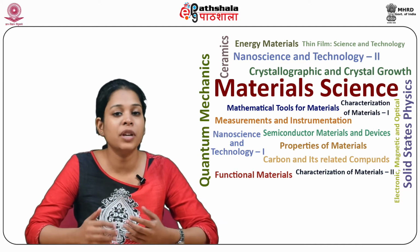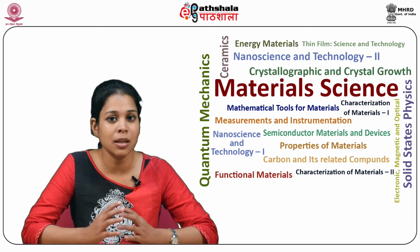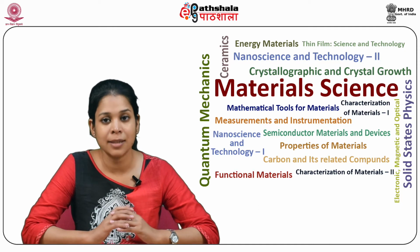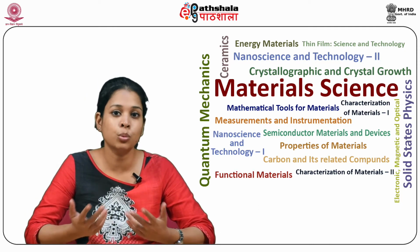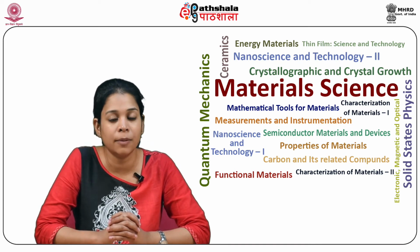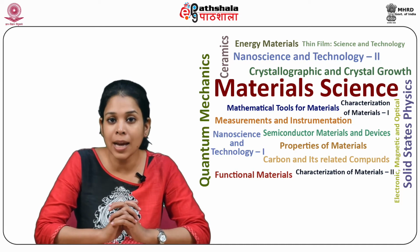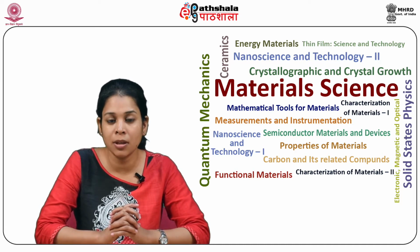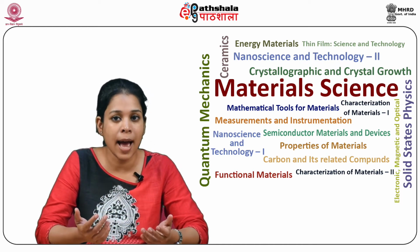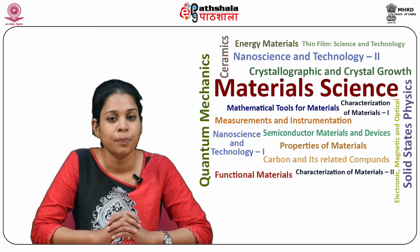Before moving to the conduction, let us discuss what electrical conductivity in ceramics is. The electrical conductivity in ceramics, as in most materials, is of two types: one is electronic and the other is ionic. Electronic conduction is the passage of free electrons through a material, and in ceramics the ionic bonds holding the atoms together do not allow for free electrons.